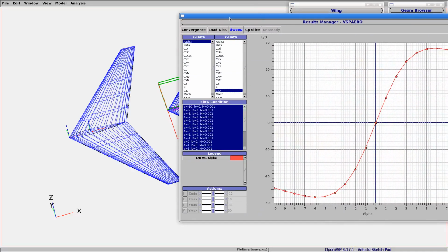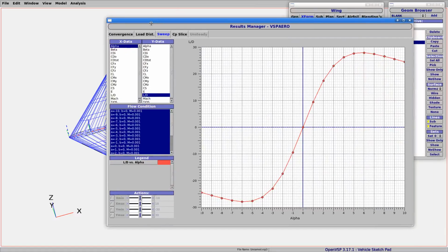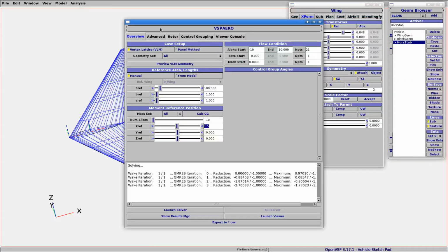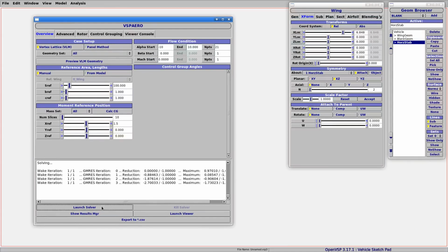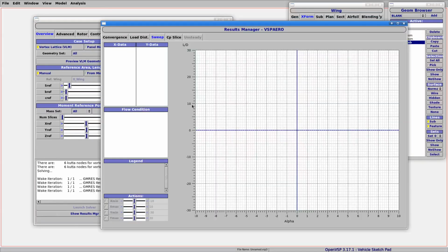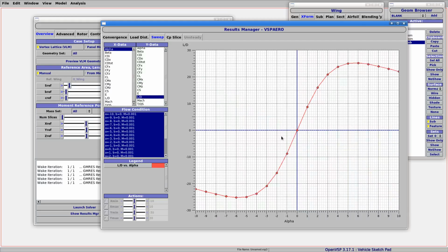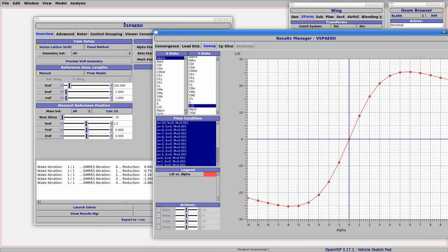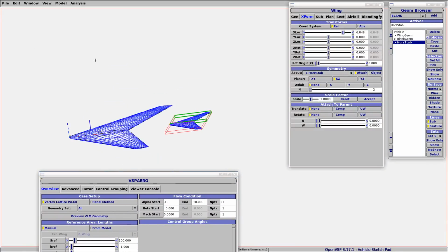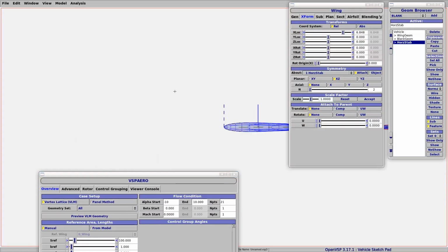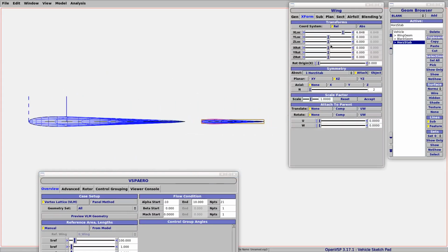it's not performing the function that we wanted. Where's my other window gone? Did I close it? Alright, let's solve it. But I'll just run this anyway and see what we get. So it doesn't really change anything for us, did it? Because those two surfaces are perfectly aligned with each other, so it's not going to do anything to change the way that the plane will pitch. So what we need to do to make that useful is the tail needs to be angled